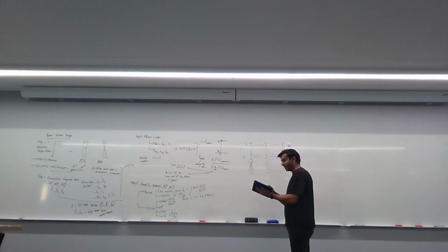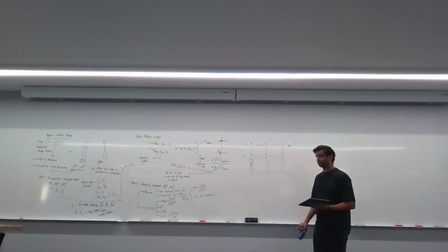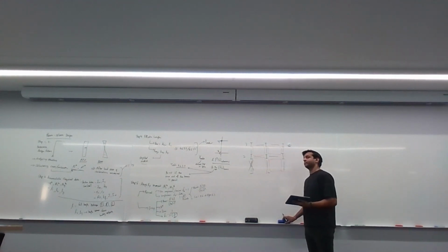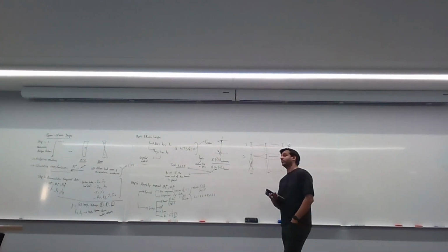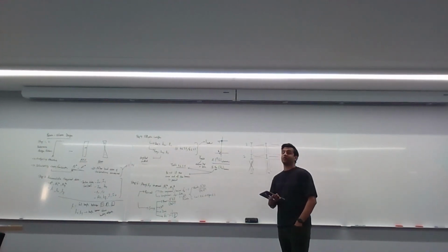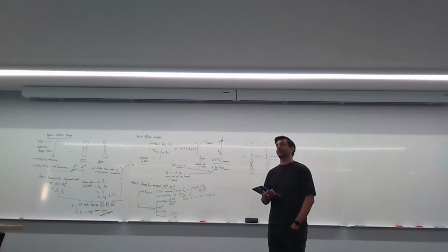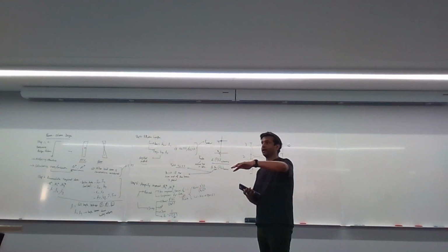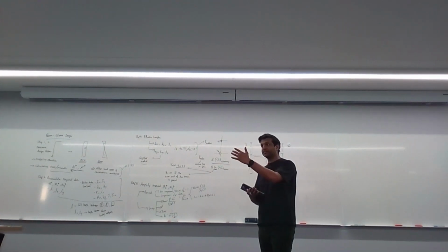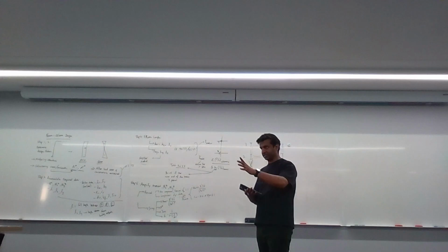So that's step 5. I think it was in week 10, there was a lecture with an example where he found both braced and sway. So in this case, would you use both to amplify the moment? Yeah, both, because it's entirely possible that in one direction it's braced and in the other direction it's swayed.